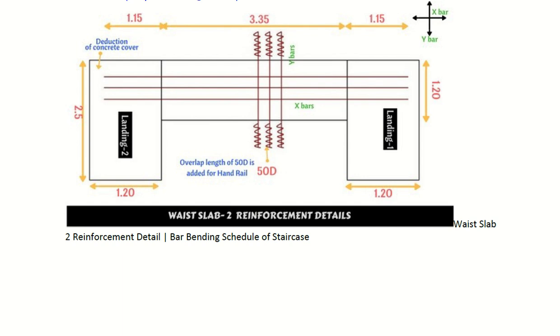Now remember, there are two base slabs. This is only showing because this is the plan view at the upper level. So there's a slab at the bottom as well. You cannot see it. But the bottom slab will have reinforcement going in this one. So the other half is covered by the other base slab. Every landing has two base slabs, right?